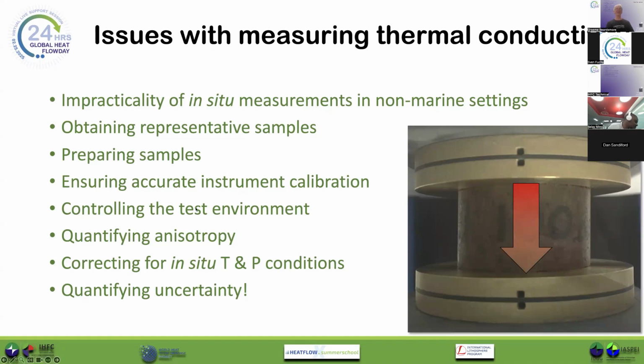The test environment generally needs to be thermally controlled, not precisely thermally controlled, but we don't want strong cold wind currents blowing through our thermal property test, because we're making subtle measurements of the flow of heat through a material. We don't want thermal disturbance happening in our test environment. So controlling the temperature and air movement through the test environment is also something we need to think about.